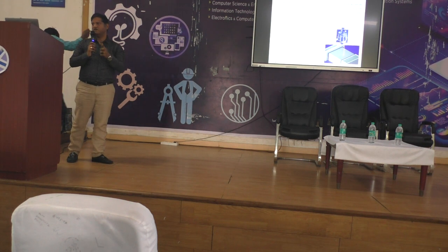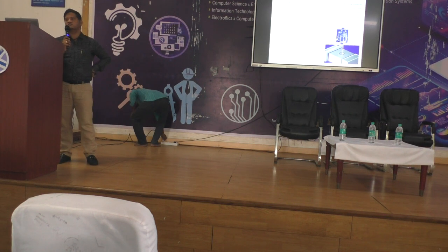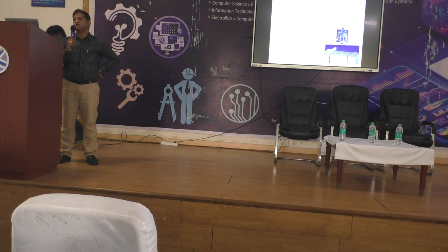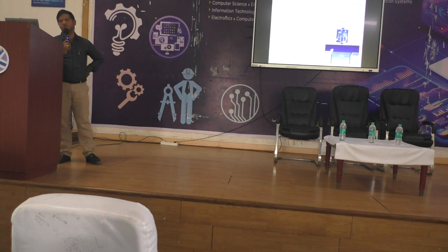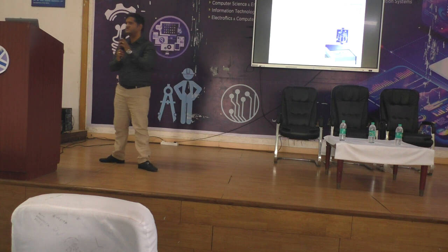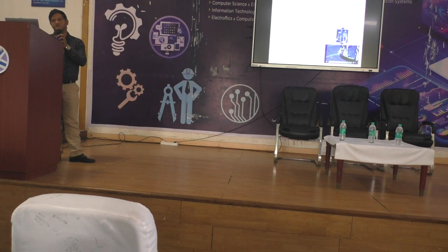So the first layer, as per the first slice information, the laser selectively melts the powder. Once it is done, the bed goes down and a new layer spreads, and again the laser traces the material as per the slice information to build the 3D component layer upon layer. In brief, this is the working principle of an additive manufacturing process.